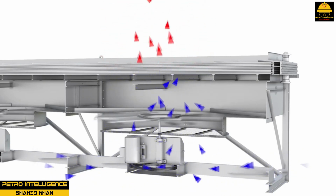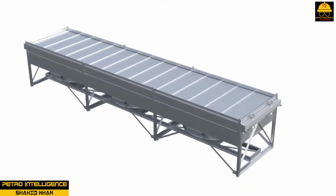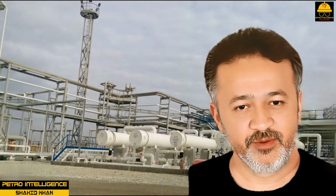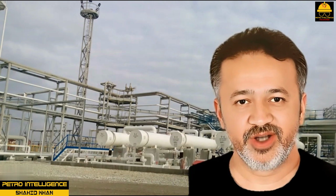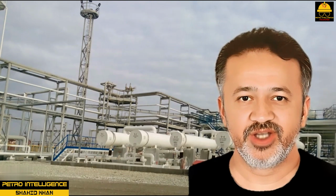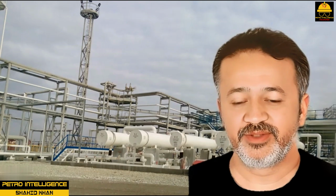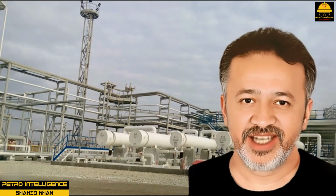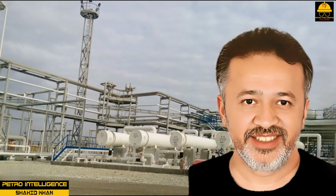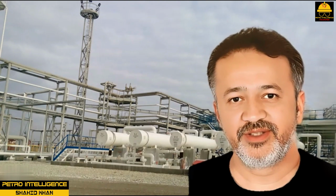Air-cooled heat exchangers can be found in service on air compressors, in recirculation systems, and in condensing operations. This type of heat transfer device provides a 40 degrees Fahrenheit or 4.44 degrees Celsius temperature differential between the ambient air and the exiting process fluid. Air-cooled heat exchangers have none of the problems associated with water such as fouling or corrosion. They are simple to construct and cheaper to maintain than water-cooled exchangers. They have low operating costs and superior high-temperature removal above 200 degrees Fahrenheit or 93.33 degrees Celsius.